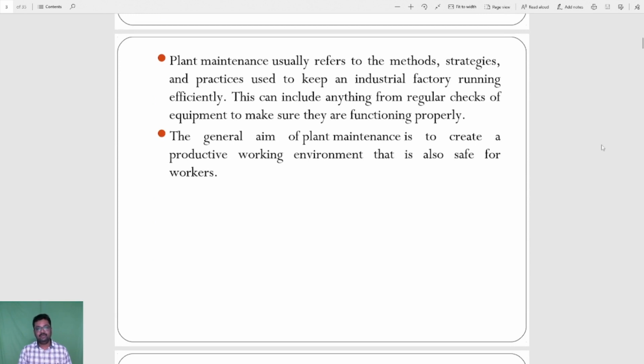There are also many strategies, because the serviceability of each and every machine varies. If we have a drilling machine, we need to service it on an hourly basis, hourly in the sense of running hours, how long the motor is running.